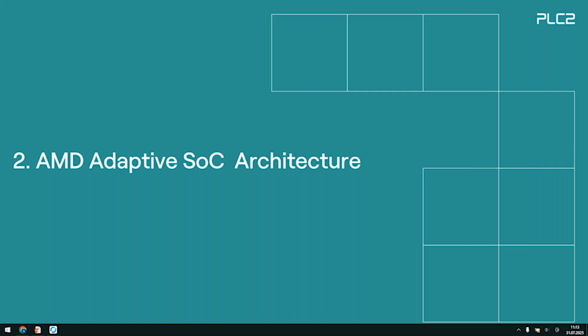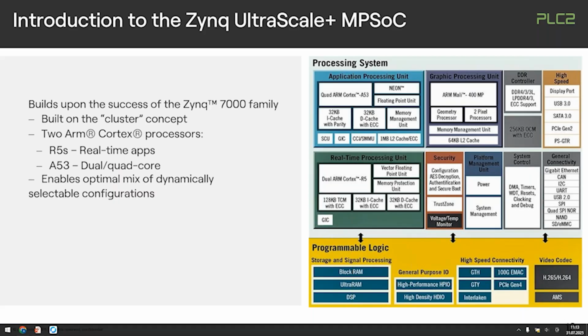So what the overall adaptive SoC architecture brings into the market is basically two families right now. Well, these are all settled on the earlier advances of Zynq 7000, but from a more complex design perspective, we're talking about the adaptive SoCs more on the Zynq Ultrascale side and the Versal side, which is in the end then a multi-core processing system. As you see on the top, this complete block here is really what is there as a hard IP on the devices.